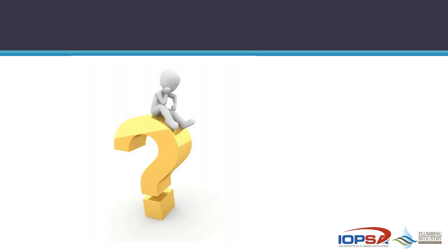I know when you do backdrops into manholes, the standard detail to those manholes is that you start from the bottom where those bends go into the channel, right up to the top where the junction goes through the wall on that backdrop, and those things get encased in concrete. But if it's a normal residential drain, there's no reason why you should backfill the whole thing with concrete.